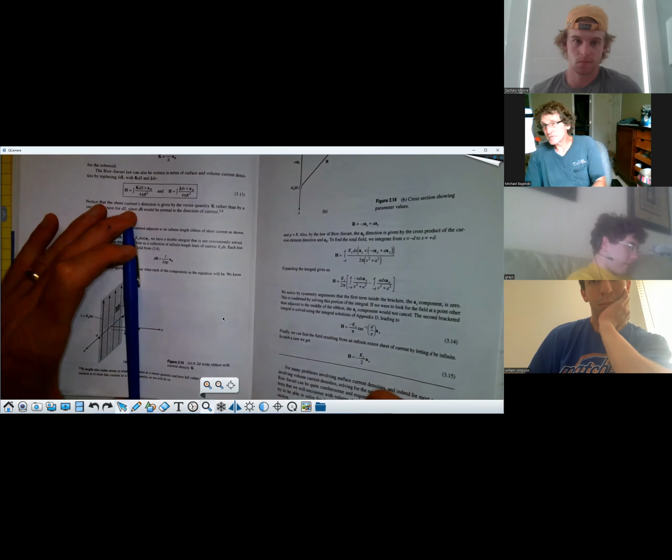So what they're going to do is this, and I'll tell you how they do it. The only thing they do is say, well, we're going to make this a very thin wire, or a thin ribbon, whatever you want to call it, that has a dx width in my drawing. So it's going to be dx times Kz, and Kz would be the current per meter flowing in the z-axis. Do y'all follow me? So if you had 20 amps per meter flowing up, that times dx would be the amount flowing in that thin sliver that's infinitely long. Makes sense to everybody?